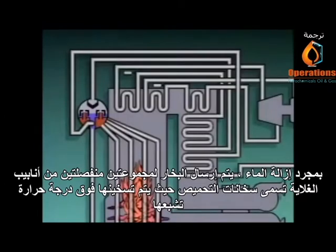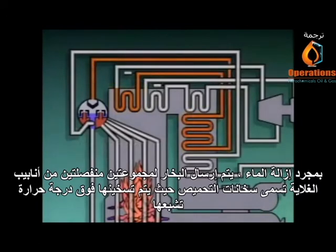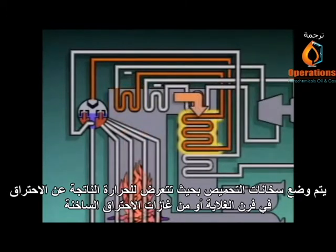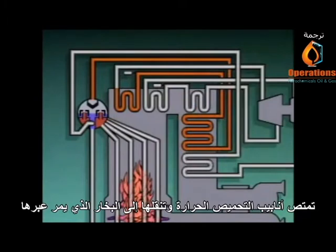Once the water is removed, the steam is sent to separate sets of boiler tubes called superheaters, where it is heated above its saturation temperature. The superheaters are positioned so that they are exposed to heat from combustion in the boiler furnace or from hot combustion gases. The superheater tubes absorb the heat and transfer it to the steam passing through them.